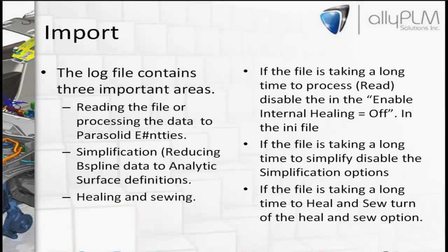So now we're going to look at the log file. So like I said, you're importing maybe a STEP or an IGES file, and it just seems to sit there. Or it takes a really long time to finish, and you're wondering, okay, what's going on here? So what you can do is if you turn on that log file option, it'll generate a log file. And there's not a lot of information in there, but there's probably enough that it'll help you to see what's going on. So there's 3 important areas in the log file: the reading of the file and processing the data, there's simplification, and there's the healing and sewing.